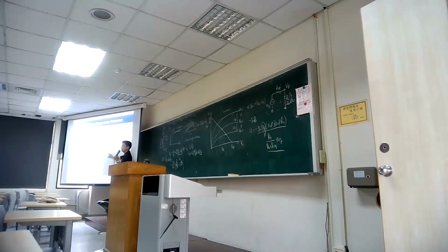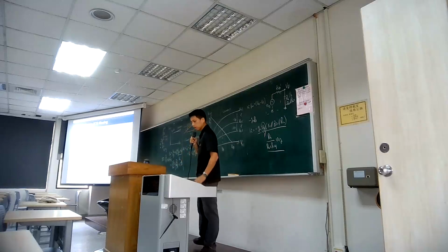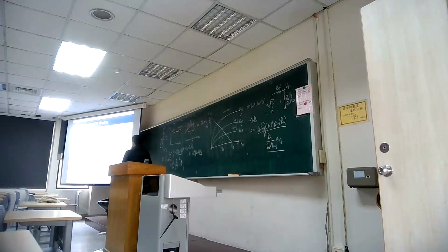The reason is because we have a capacitance around the transistor. If you look back to the capacitance we use, there will still be at least 2 capacitances at the input and the output pole. So if you want to improve your low frequency response, typically you use a large capacitance in order to push the low frequency response down further. I'm not sure how many people use bass when you watch TV or hear music. Bass means that typically a large capacitance is required. So if you work with bass, the system is large. You need to use a large capacitor.